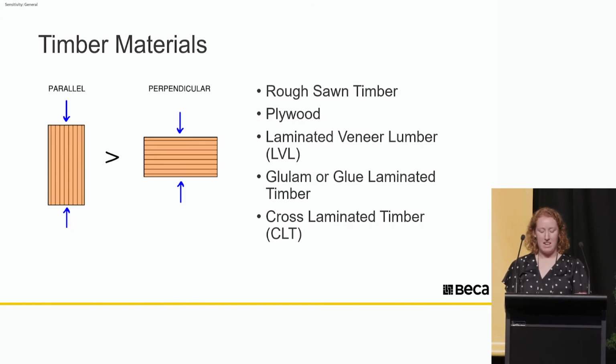I watched a webinar series early on in this design by Wood Solutions, which among other topics talked about some of the basics of timber. One item that stuck in my head was that timber is like a bundle of straws. That bundle of straws is now how I visualize timber when I'm going through material and connection design. Timber is stronger parallel to the grain, just like a bundle of straws if you push down on the ends. Perpendicular to the grain, if you squeeze the straws, it's quite weak. As a rule of thumb, I don't try to carry significant loads through timber perpendicular to the grain.